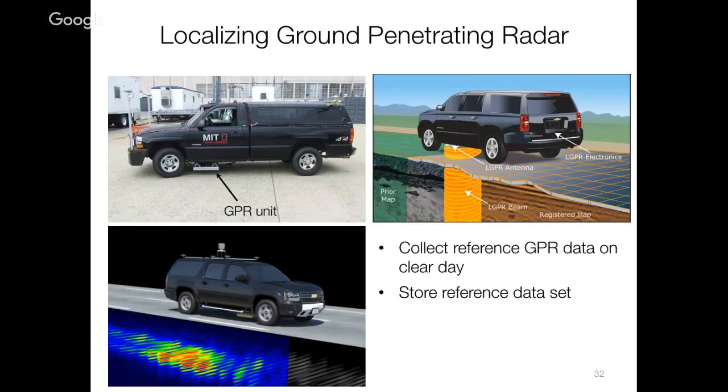So here's the ticket. You're going to use GPR. What you're going to do is take a GPR unit and mount it under the truck. Okay? So there's actually going to be a whole bunch of little GPR systems, transmitters and receivers, mounted in here. And then at any particular time, if you set these off, you get a radiogram that comes back for that location.